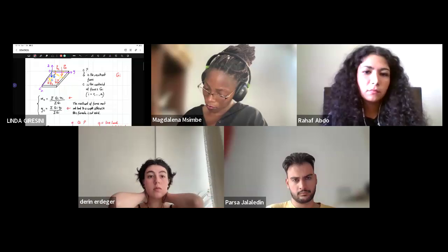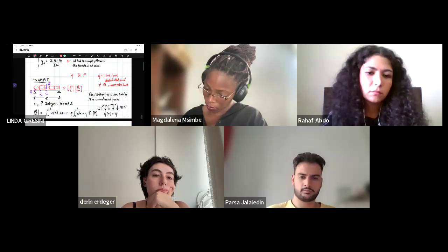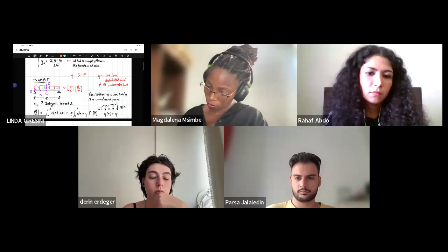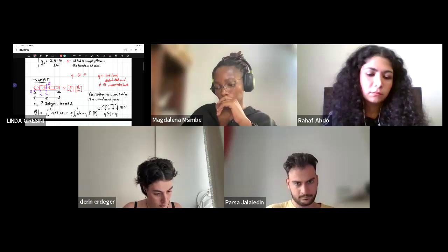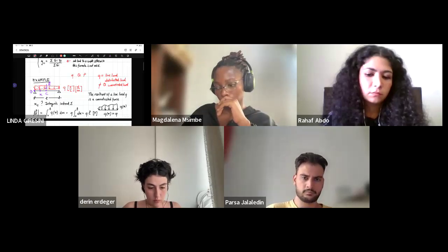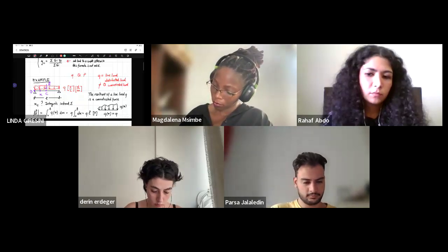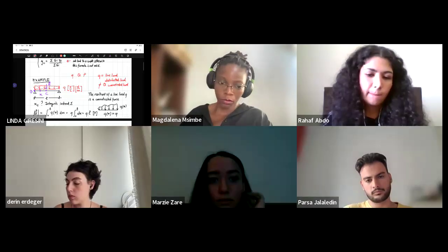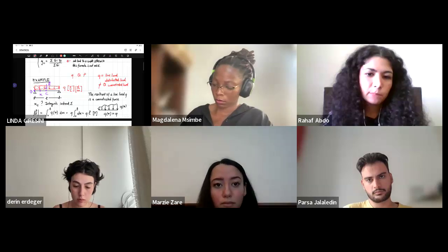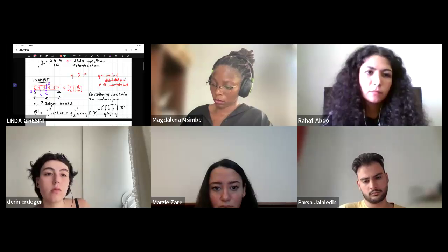But in case we have line loads or distributed forces, as it was the case of the first example that we have here, we need to use the integrals, so instead of the sum of discrete elements, so discrete forces in this case, concentrated forces, we need to use the integral, okay? In that case, it was quite simple because we had the uniform line load for all the beam length.